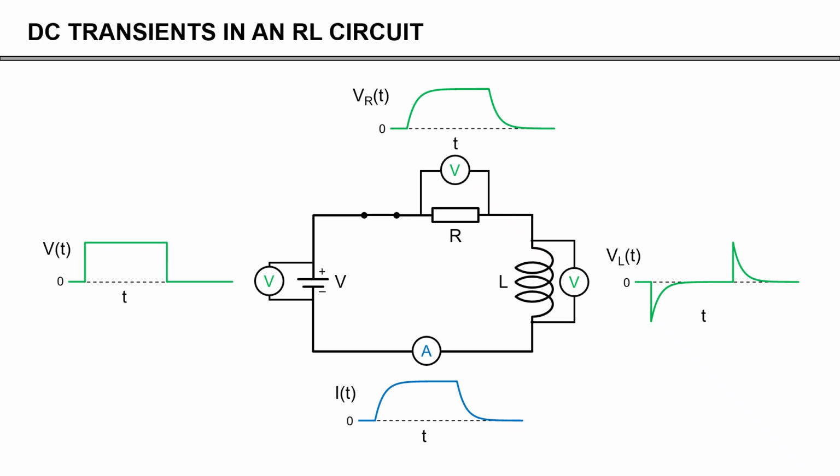If the inductor wasn't there, this was an instant rise, but because of the inductance, the rise is much slower. And then when you turn off the input, it will linger a little bit. It will exponentially decay. And the exponential time constant is basically the inductance over the resistance. So this is one component that we need for our radio frequency coil.